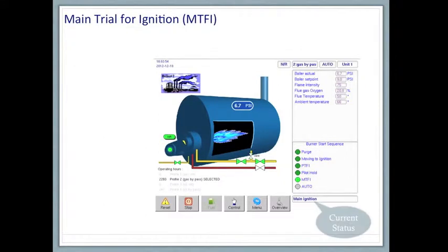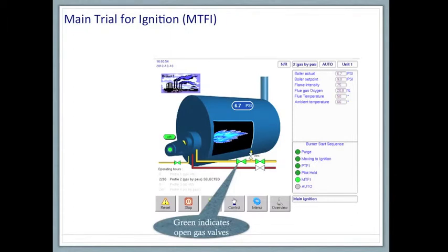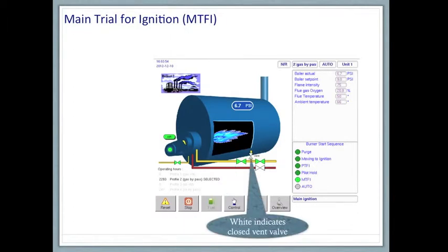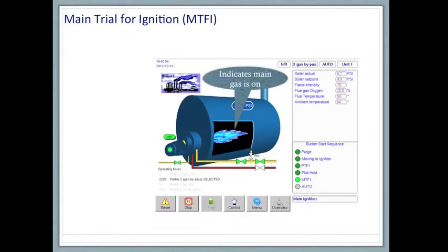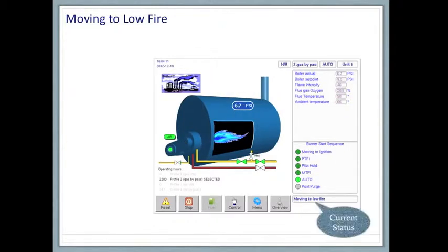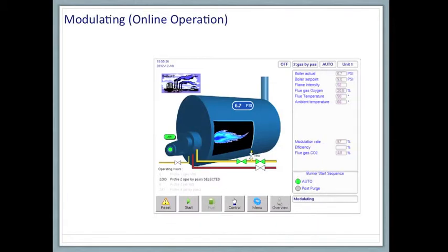The controller confirms all required drives are at their ignition position and gives an ignition-proof signal. The controller will hold the drives at their respective positions until the signal to modulate is received from the burner controller. Finally, the fuel and air motors reach their low fire positions where they will then modulate according to the demand placed on the burner.